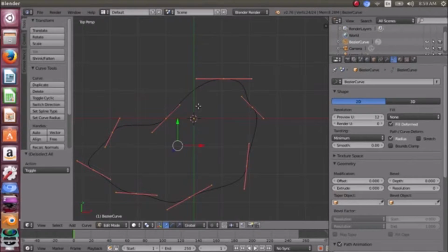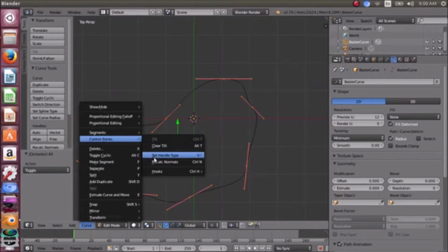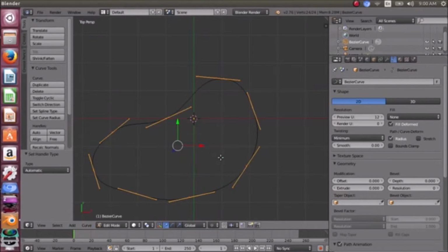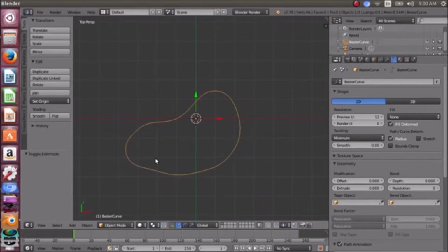So you could modify the program, for instance, to work on an open basis, but I've done it on a closed basis. So what I've done is I've got all these curves, or the points added to the curve. Now, if you want to smooth the curve out so that there's a little more continuity going from one anchor to the next, you can do so in Blender quite easily. And that is in resetting the handle type to, say, automatic, and it kind of smooths it out so that we have a more continuous looking curve. If I go into object mode, that's what the curve looks like.